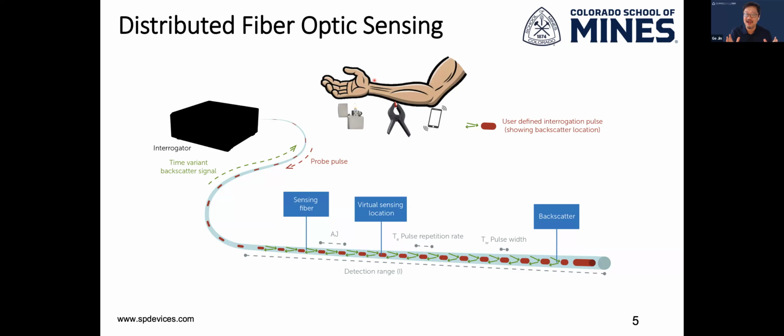So at any time, at any location along the fiber, we're able to measure temperature. In this particular case, we're able to measure the strain, whether the fiber is being extended or compressed, with very high spatial and temporal resolution, but also very high measurement sensitivity. At this point, the modern instrument can even measure up to nanostrain, extension and compression along the fiber.